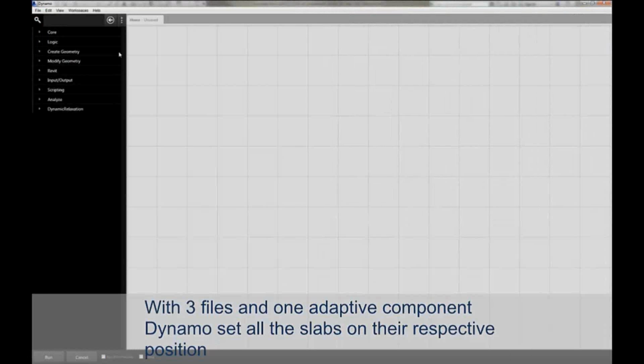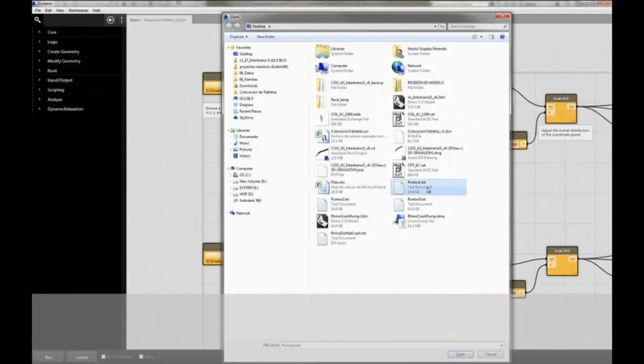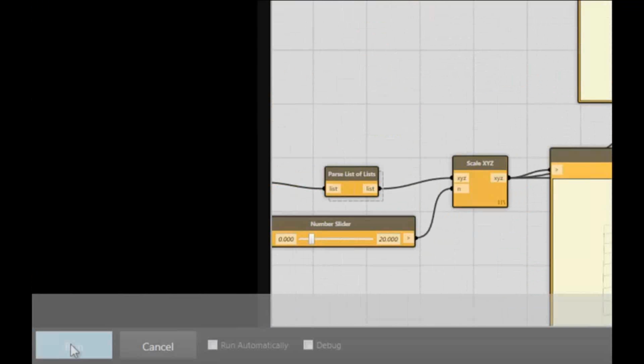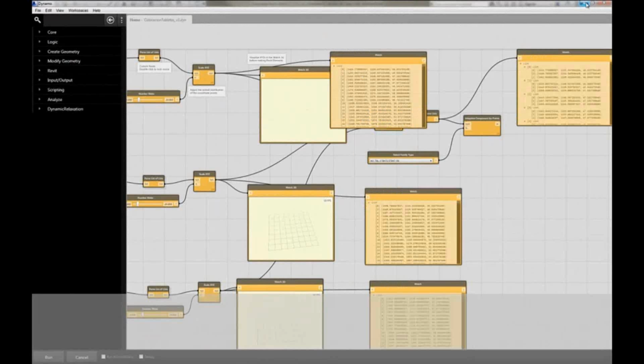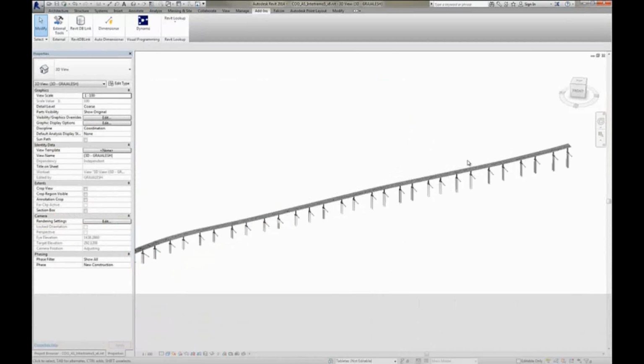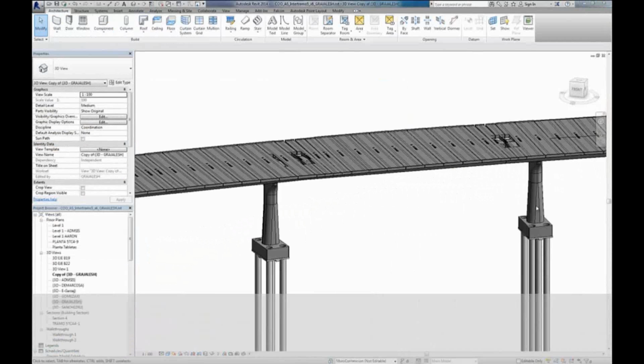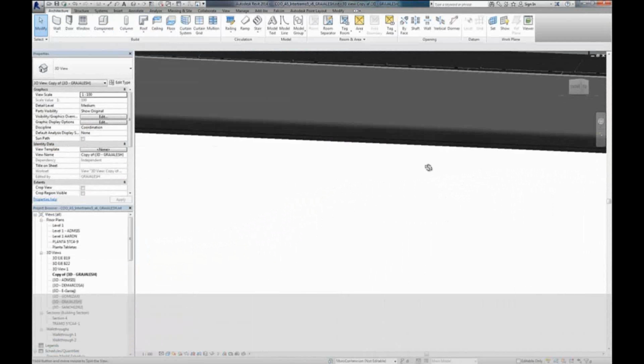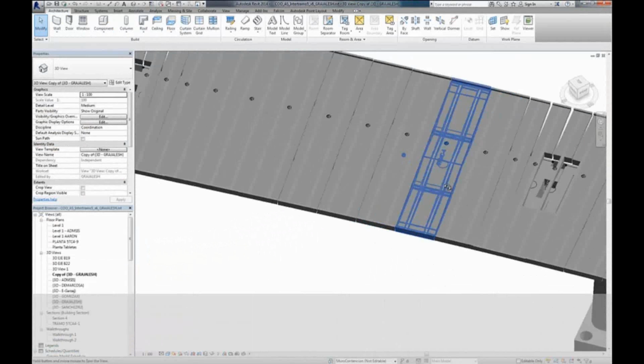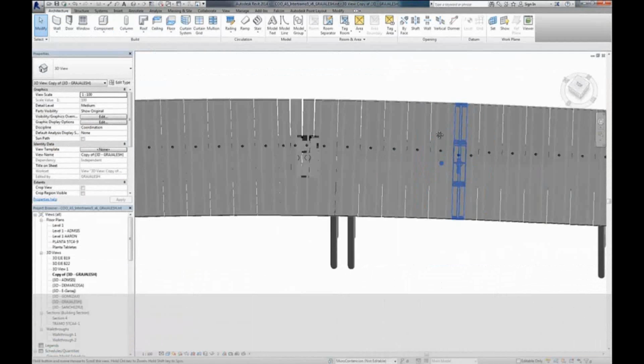The basic idea here is that they're working with a civil engineer that's creating essentially a centerline position, and they're reading that center line and the points along it to start creating a raised roadway without having to manually place all of the columns and foundation members and then the superstructure. They're able to use Dynamo to instantiate all of that.